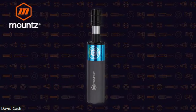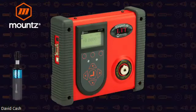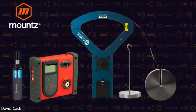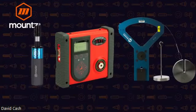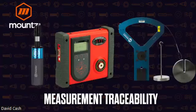And so if we look at the actual traceability of how this would work, if we were to calibrate a torque screwdriver on a torque analyzer, that screwdriver is traceable to that analyzer. The analyzer then is traceable to the calibration of the segment arm and the weights that are being used for the calibration of the torque analyzer.